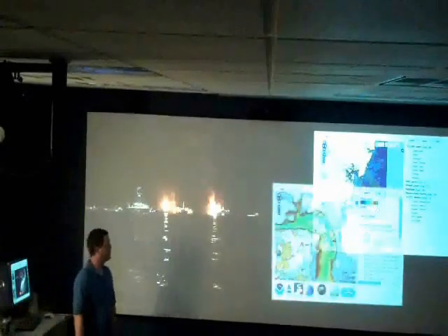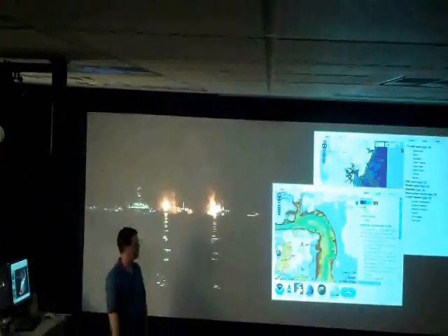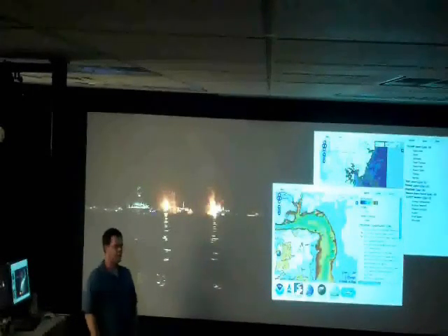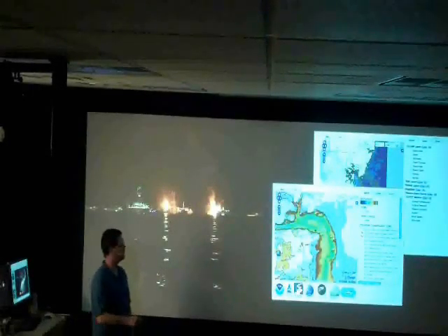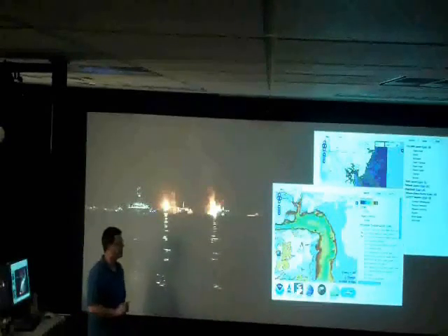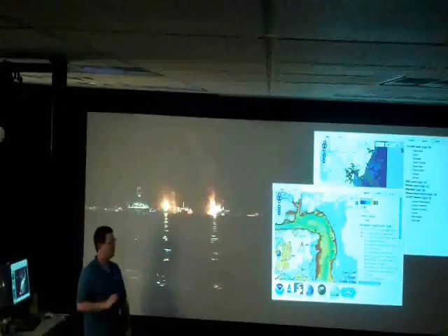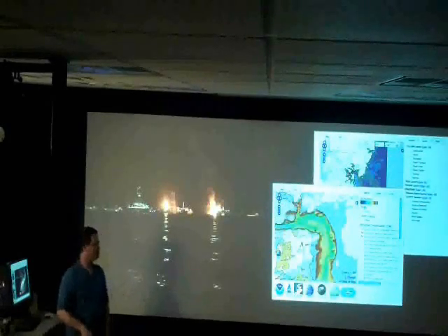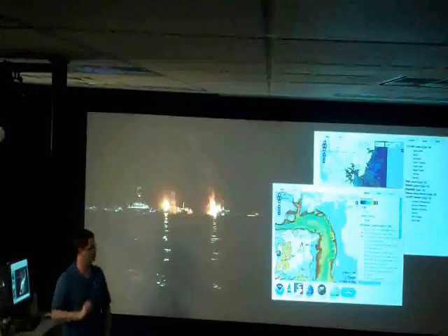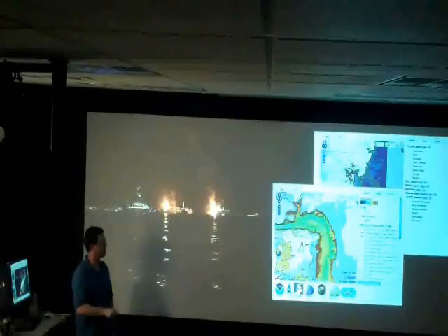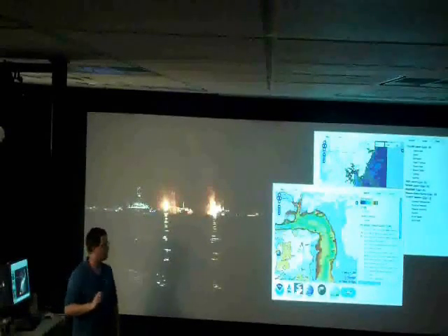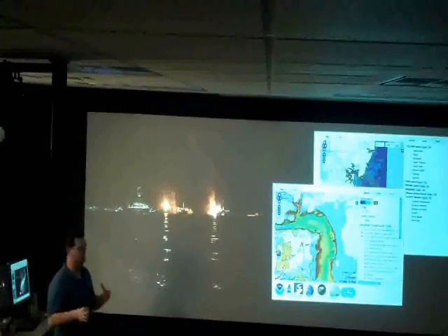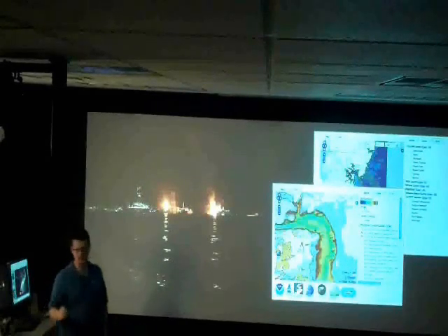And then we started looking at what we could possibly do. Can we get bathymetry in there? Well, it's not a 3D interface like GeoZui or Fledermaus, but you can make a nice GeoTIFF and drop in a GeoTIFF pretty quickly with these tools. We use something called GDAL to take GeoTIFFs from tools and just drop them right into an interface where you upload a file, and magically you've now got a new layer with your bathymetry in there. We started working on how to get legends. Legends turned out to be a royal pain, making nice icons for things and making them show up cleanly from ArcGIS or some of the other tools. Ended up being a lot of time.